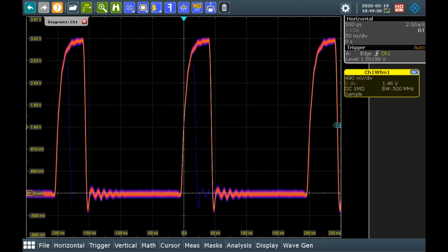So analog scopes are still great if you can find them. Most people aren't making new analog scopes, so that's the first challenge. The second challenge is that analog scopes are typically limited to a couple hundred megahertz, and we're able to do this high update rate all the way up to 16 gigahertz now. So it's really a cool way to look at high-speed signals with this high update rate as signals are changing quickly.